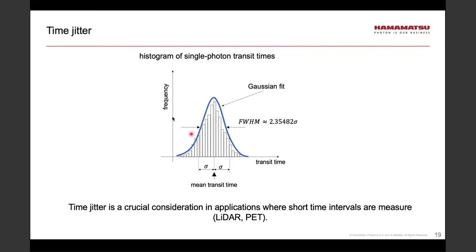So because of these variations, especially with the number of photons, it is customary to represent this plot for single photon illumination. So one has to be careful. If I see a plot of time jitter obtained with a single photon versus one obtained with, let's say, 100 photon illumination, they are not comparable. We are comparing different things. Something to make a note of.